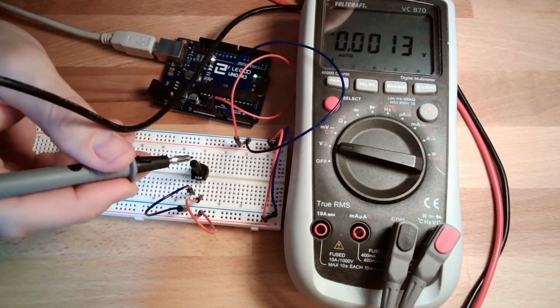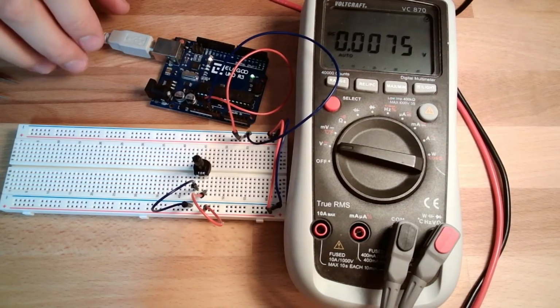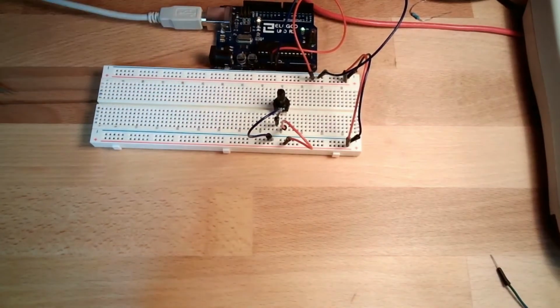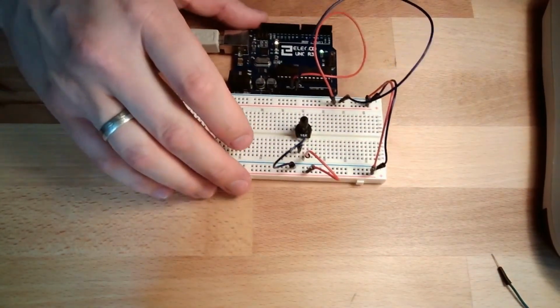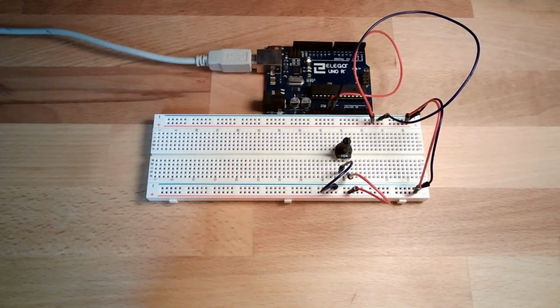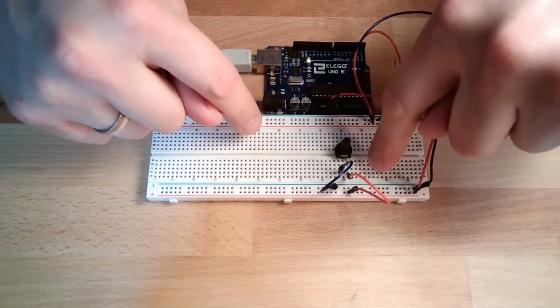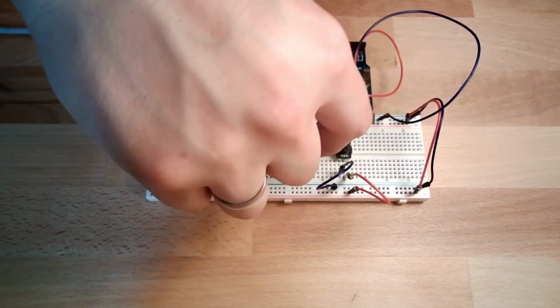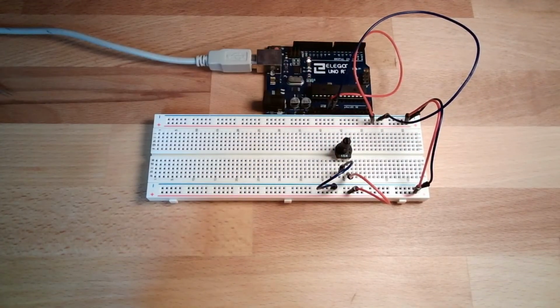This thing here is called a potentiometer. This one we will use to test our analog input. So one end plus, second end minus. In between, we do not have, like before, 3 kilo ohms. We have 10 kilo ohms. That is why 10K is written on it. And here, this is the so-called sliding contact.